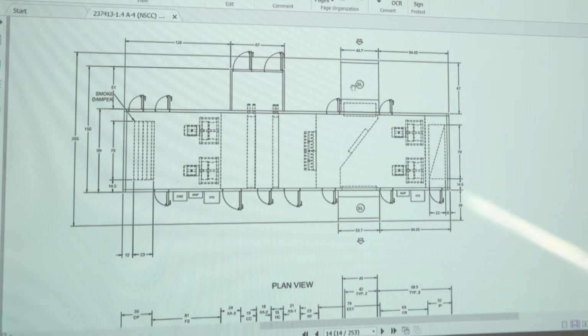You'll see that you have your outside air intake dampers, your mixing damper, your exhaust air damper. Okay, so as the air returns from the unit, based on the requirements of the discharge air set points, you'll have a certain amount of defined air exhausted. You'll have a certain amount of air that returns back through the unit. You'll have a certain amount of air that's brought in from the outside. And then you'll pass through your coils. Okay, your heating coils, your cooling coils, your supply fans, discharge opening in the unit.